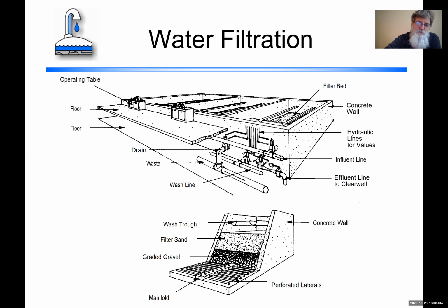And here's just a picture of a large industrial municipal system. You can see that there's one filter, two filters, three filters. So this would have three filters on one side. Typically on the other side of the building, there'd be another one. They share a basement system where all the pipes that bring the water in, backwash pipes, collection pipes, input pipes, maybe what's referred to as a pipe gallery. And then you can see below what a cross section of a typical system is. We've seen some of these before. I just thought I'd show you some different views.